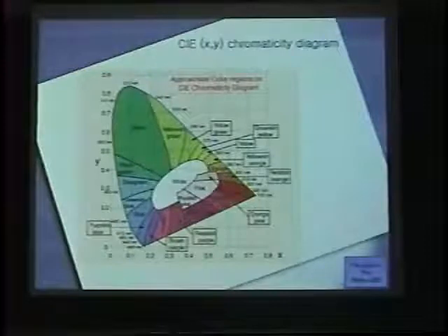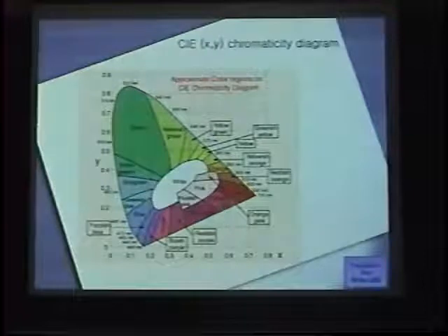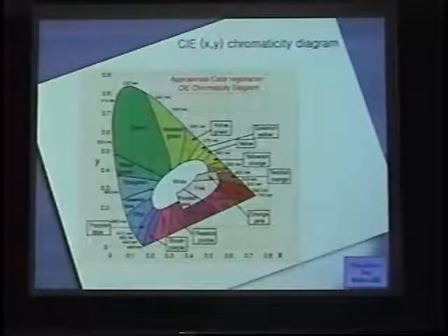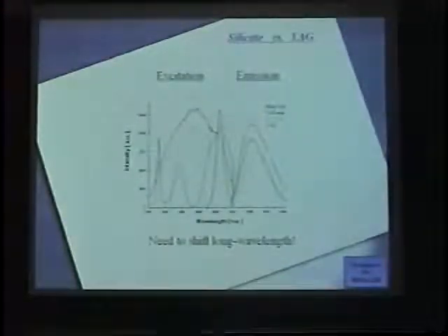So what kind of phosphor do we need? The most important thing is color. You see, red, green, blue. In the case of a UV LED, the most efficient chip is near 405 nanometers in this region. If you have a UV LED, you see a kind of violet color from that chip. So if you put red, green, and blue phosphors on it, then you can get to the white point here. At this moment, take a look at another side.